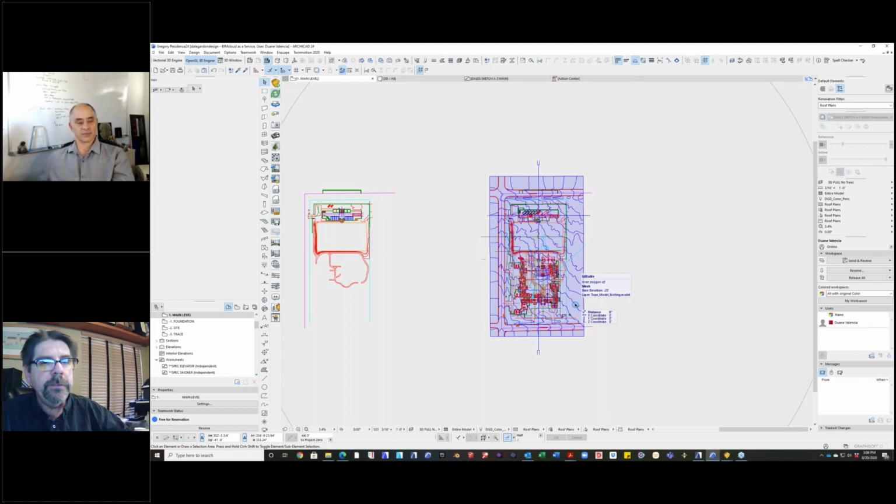So my civil engineer sends out his drone guy, and his drone guy converts the drone flight into a point cloud, and then the point cloud comes into ArchiCAD as, in my case, pretty much the exact mesh that I have here, but in point cloud. So it's shooting in all directions, identifying the color of each pixel that it sees, and so it's not an entity, it's just a bunch of points. But when you look at them all together, it looks like the site in color.